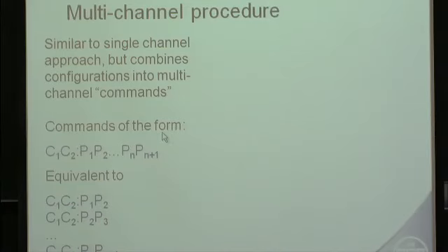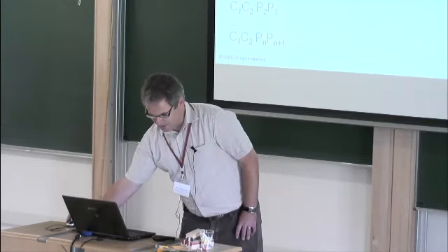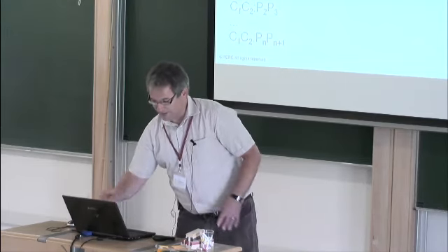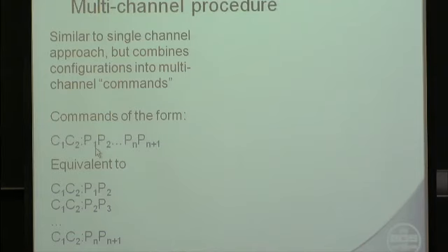The meters we use at BGS, the configurations are measured in this form. You have a pair of current electrodes, and then for that current injection you measure multiple potential differences. So we have a 10-channel system, so n is 10, and we measure these 10 potential differences. So you measure a difference between P1 and P2, a difference P2, P3, and so on up to Pn plus 1.